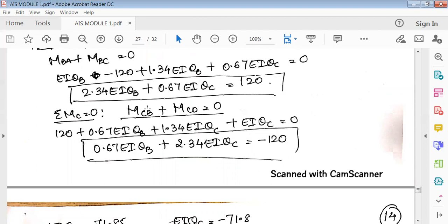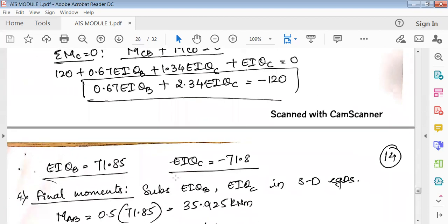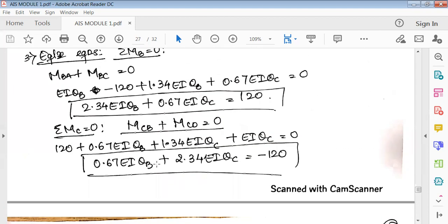Again, use these joint equilibrium equations and substitute in the calci. So solve this using the calci, because things become easy. I've already told you, again use the equation form. There are only two unknowns here. So again, in the calci, press mode 3 times. You'll get equation, so again press 1 in that. Then you'll get two unknowns. So choose two unknowns and start substituting these values.